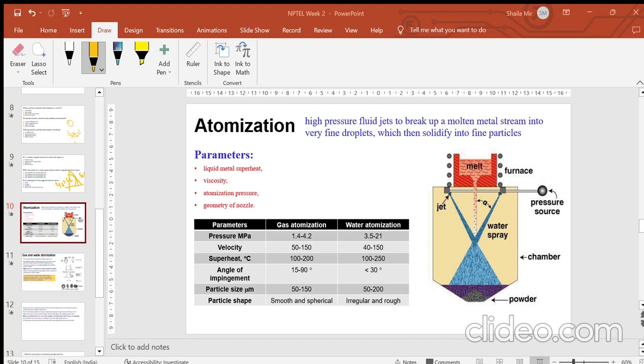So how are we approaching this? First, it is clear that in the stages of molten metal disintegration, wave is the first thing formed. That is, the flat surfaces, flaky substances are formed. Once those flaky substances are formed, they are further elongated and they form ligaments. Then fine droplets are formed because there is a continuous impingement of the water or gas.